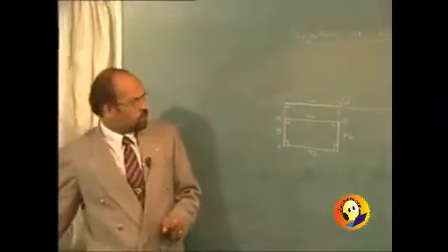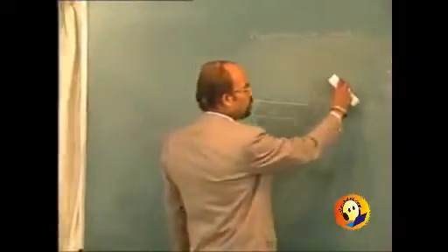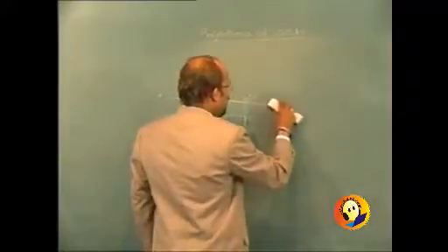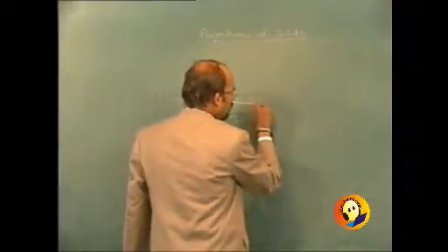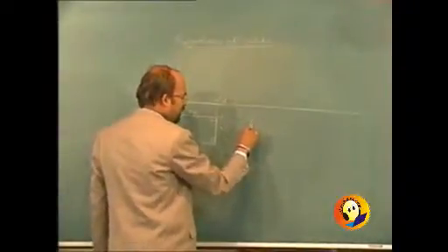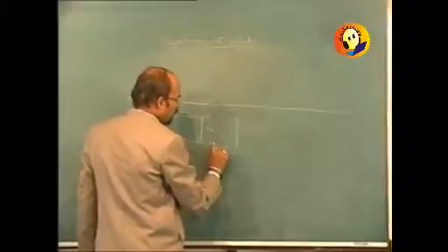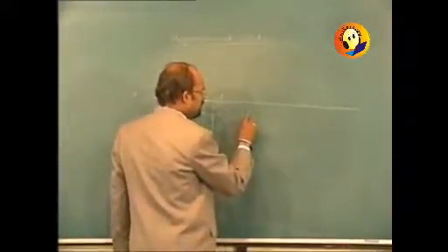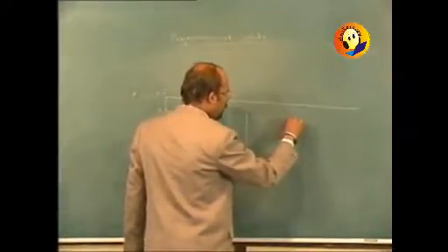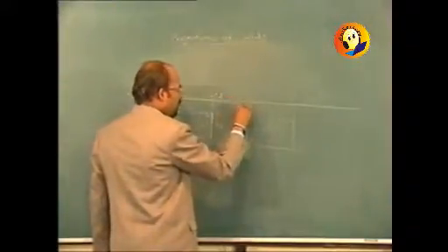Now when projections of planes is considered, at the second stage we were talking about the plane inclined to, say, horizontal plane. In that case we have said that the line of rotation should be perpendicular to XY, and suppose this rectangular lamina itself, if I plan to turn about line AB,